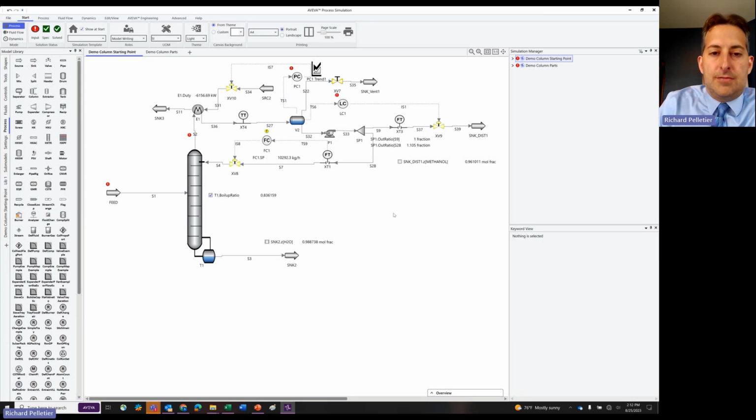If you don't have that as an option, you would have to build this out. And so what you would do is you drag and drop the heat exchanger. You'd disconnect from the sink and you'd connect the overhead to the heat exchanger. You'd add in the other side of the heat exchanger. You'd add in the product going to the drum, right? And you'd add in this drum model, and you'd literally go one model at a time until you build out this entire network and reconnect it back to the column. So that's how you would do it if you're doing it manually.